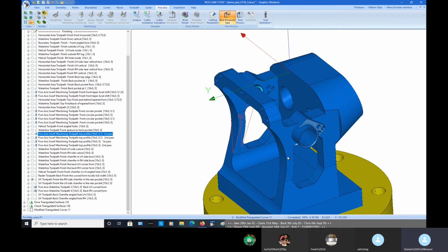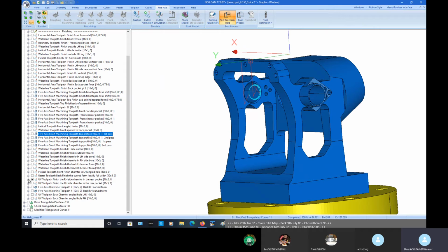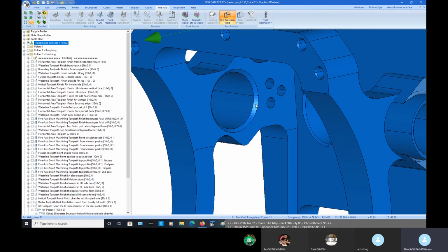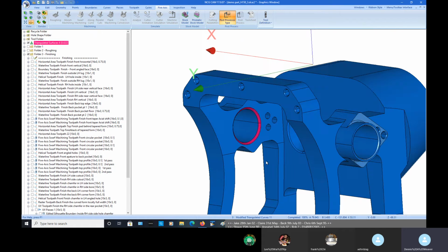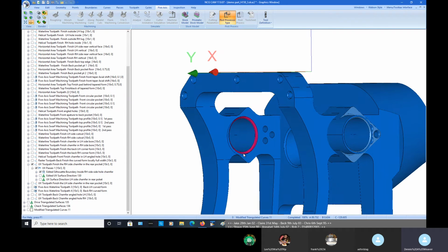Okay, some tricky undercuts in order to get these chamfers on the back. What's happened here is we have selected the chamfer surfaces and created UV toolpaths on them. So we've selected those two surfaces, and there should also be a silhouette boundary to give it a direction. So we've sorted out the silhouette boundary at an angle in order to give us the tool axis that we need.